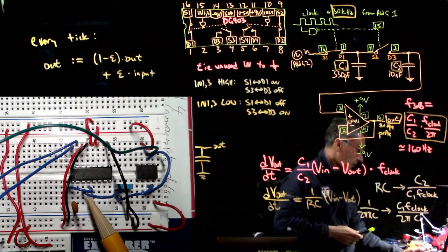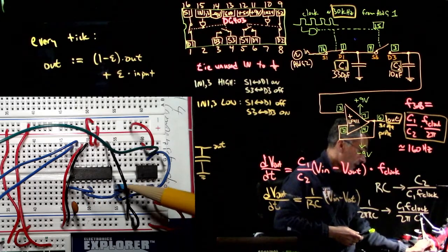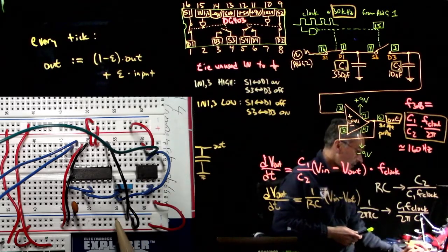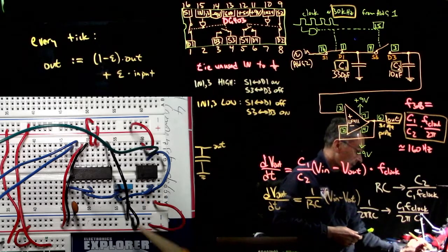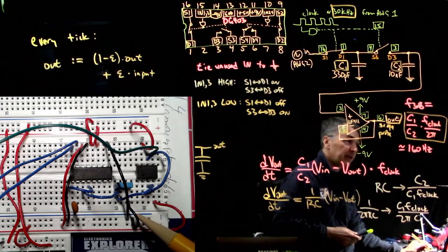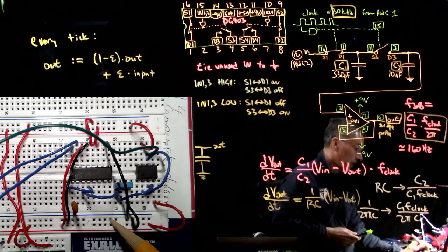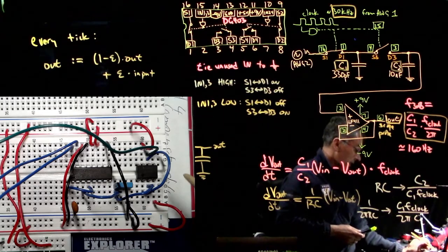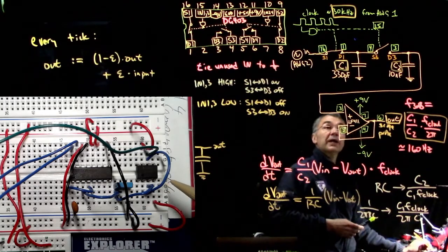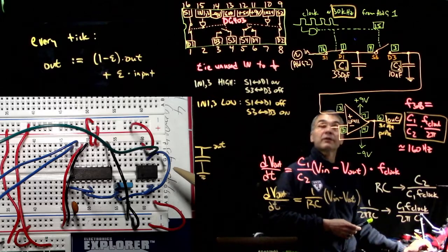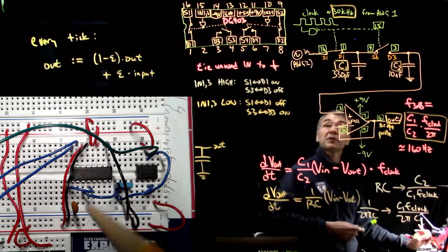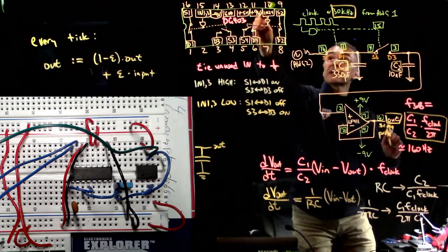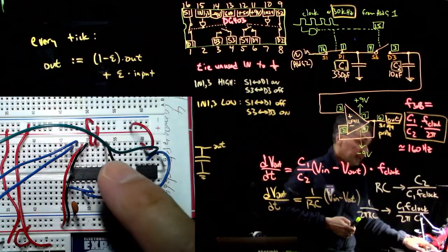This little wire goes from pin 3 of the DG403 over to the left side of the capacitor. Then that same left side of the capacitor goes over to pin 3 of the op amp, the LF411. The right-hand side of the capacitor has this little black wire going to ground. This blue row here is ground. I think that's everything except for power. We have the usual power connections on pins 11, 12, 13, 14 of the DG403, and this unused pin 10, I connected to ground. You can see where I did that here.